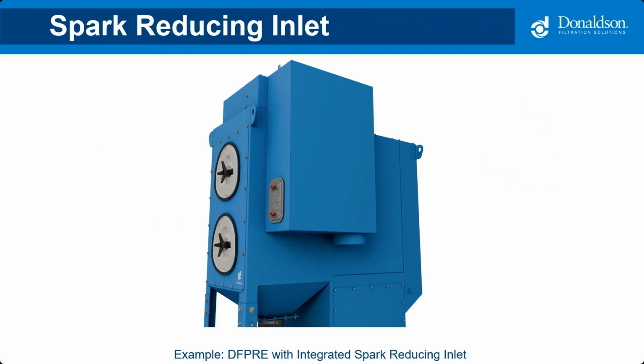Here's an example of a spark-reducing inlet that we use on our DF pre-collector. Essentially, as the air comes up from the bottom in the inlet, it forces the air through a tortuous path, and that air will then travel through different directions, which helps knock down the sparks.